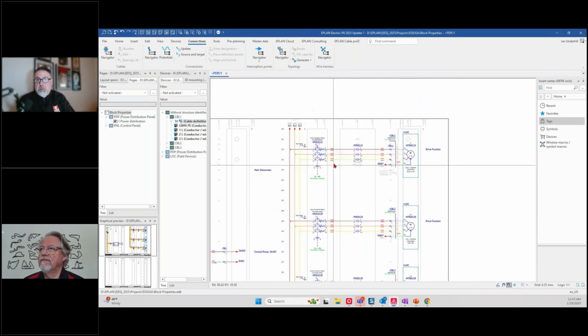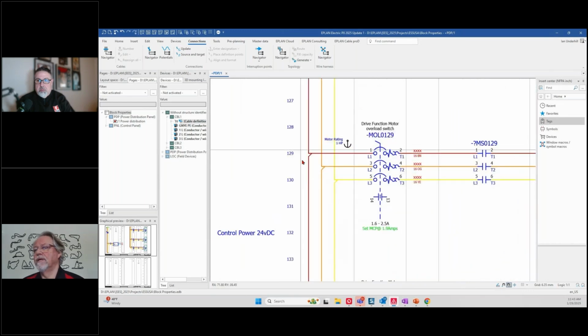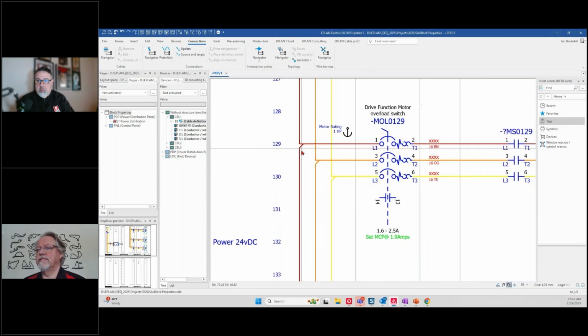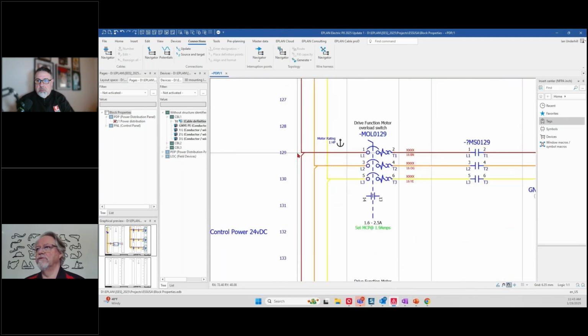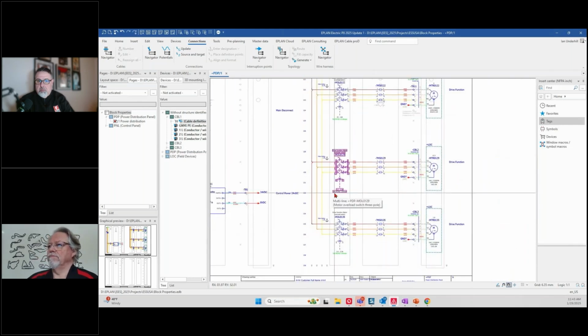These are daisy chained together, as the user has just said, by virtue of the way the T node goes. So the T node, for those that are not familiar, this would say that the wire comes down, goes into this device, and then back out to the next device. So I know that directional flow works. So in this instance, it works no problems.